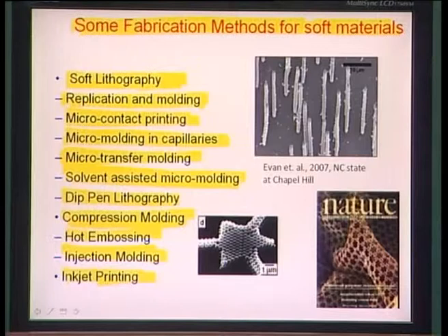Okay. So some illustrations here very wonderfully shown. This is a paper reported by Van et al. 2007, wherein he builds these high aspect ratio features and structures. As you see, this is about 30-40 microns in height and only about 2 microns in diameter or so. This kind of high aspect ratio structure is formulated by putting an additive into the soft polymer polydimethyl siloxane, and then using some kind of a mold to make these cilia like moieties.